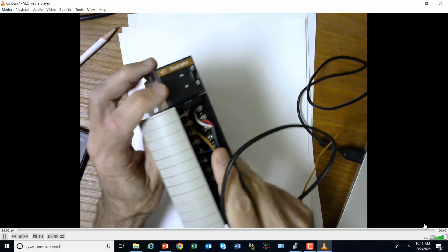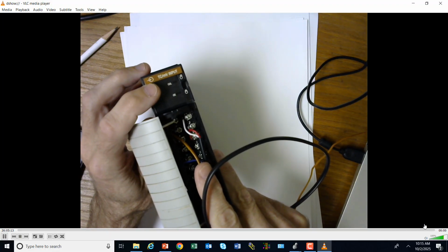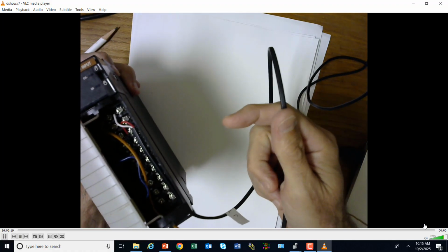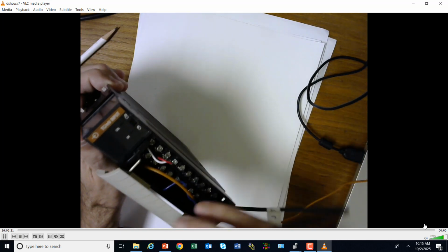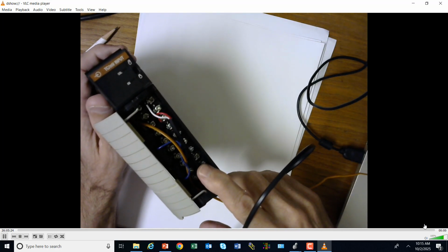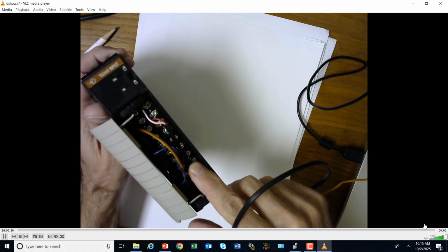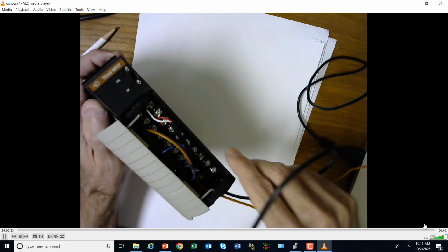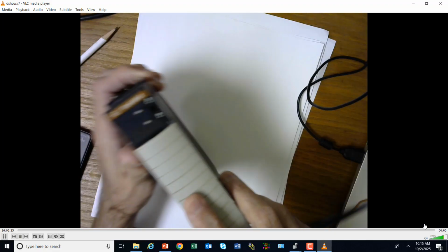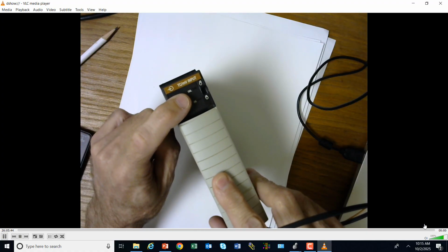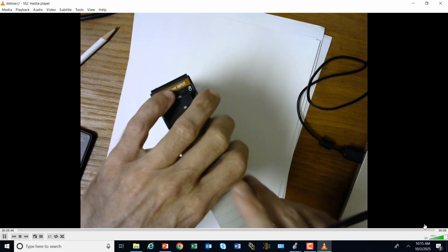Anyways, talking about the thermocouple demonstration. So this is a thermocouple input module, which is very similar to the analog module that we're using, and we'll be using this next week, and it's got some thermocouples in it. But the wiring in here is going to be a little bit different than the wiring that we've done on sourcing and sinking input and output modules, digital input and output modules. And so the thing to realize is that this is not a linear device. It's a thermocouple, and thermocouple response is not linear, whereas the analog that we're wired into is going to give us a linear or proportional curve, and we'll be doing some math on that here shortly.